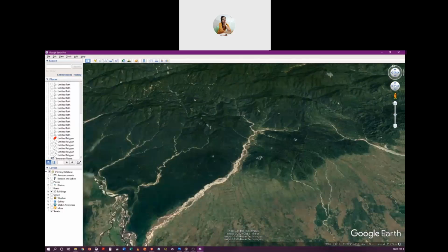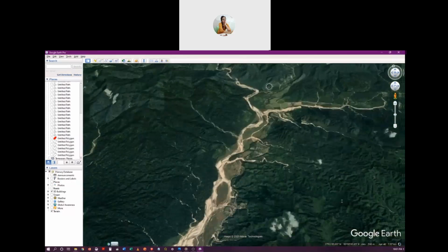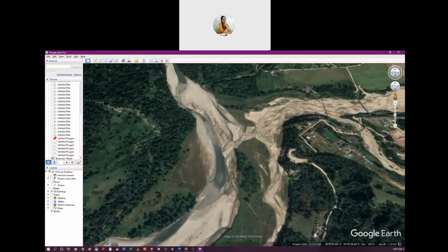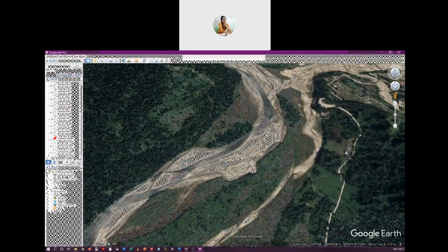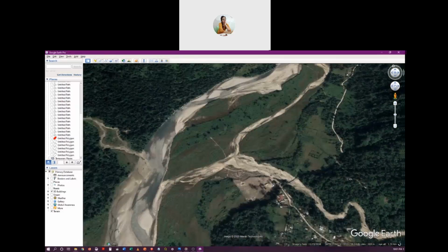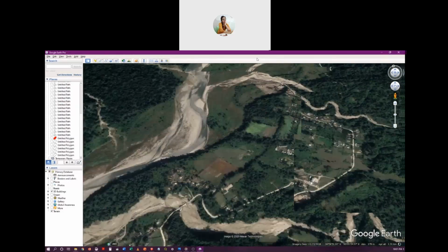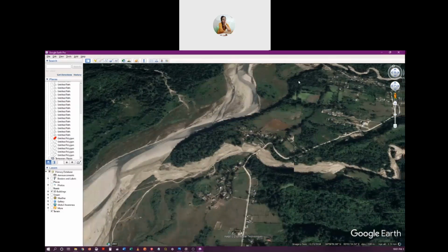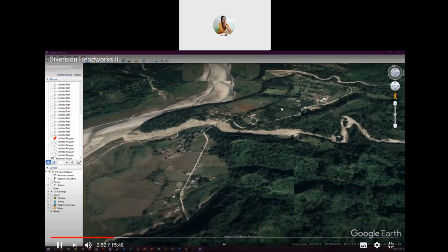And that's why if we construct a project in the upstream regions, although we have a greater command area, we'll not be able to carry the water through a canal economically, because it will have to cross lots of mountains and natural drains, and that is not a trivial task. Either you'll have to dig tunnels through these mountains, or you'd have to make some cross drainage works.